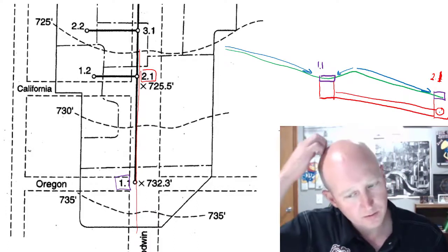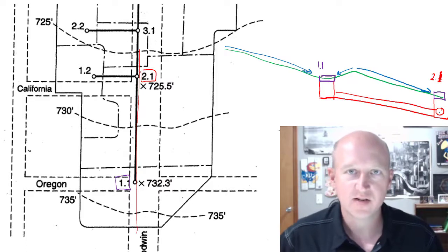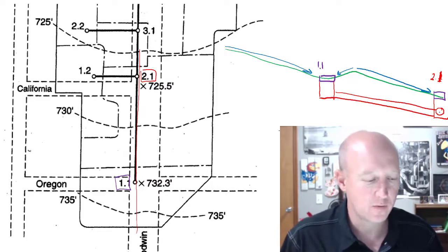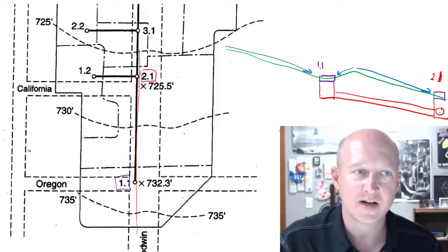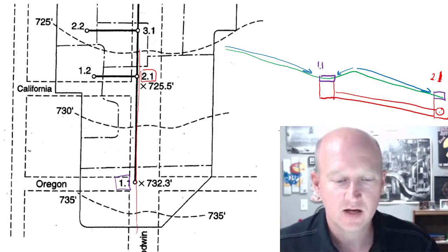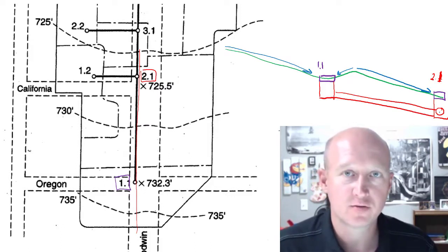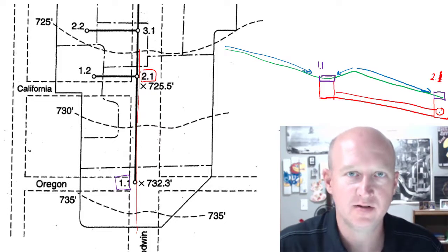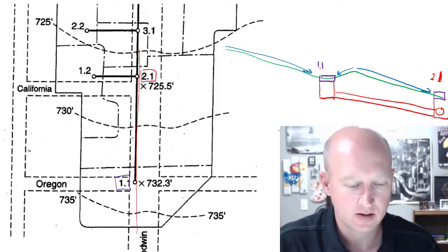So what we need to do is first discuss how to design the inlet structures. And essentially what that means is that for a certain amount of water that will be running to the site, how big does the inlet need to be? And that's going to be a function of the duration of the storm and the return period that we're designing for. So the return period is typically going to be defined by a municipality or local governing body.